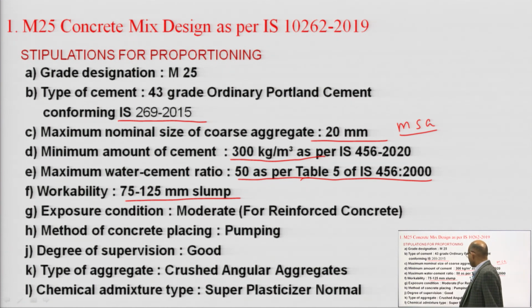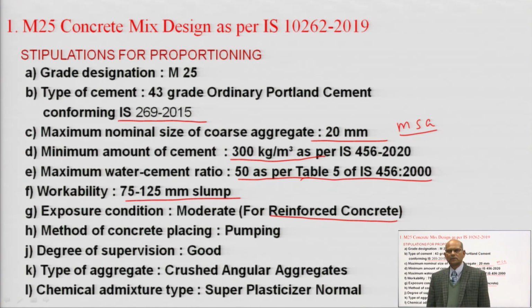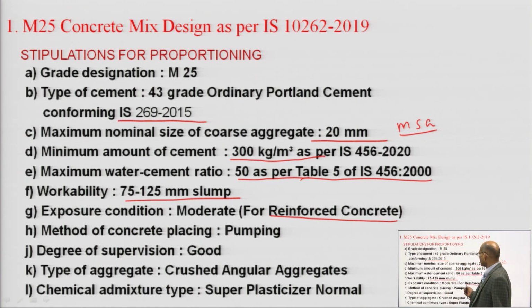Then we have the exposure condition. The exposure condition is moderate. A bracket is given for reinforced concrete. So, for reinforced concrete we have to consider the workability and exposure condition, because you have two conditions: one is reinforced cement concrete, another is plain cement concrete.